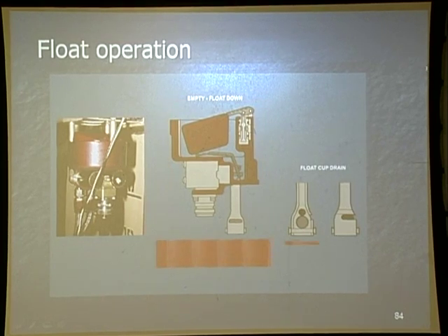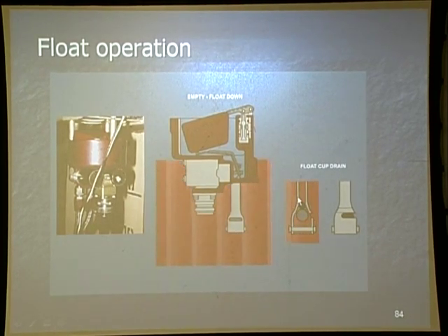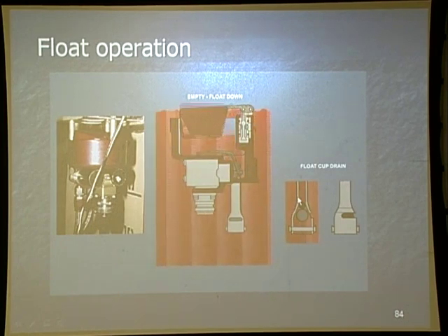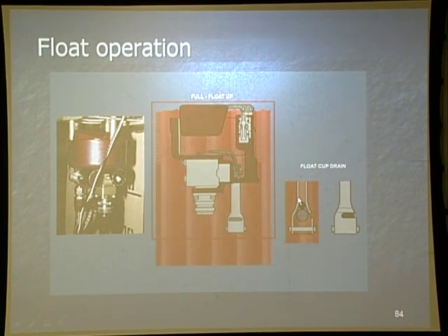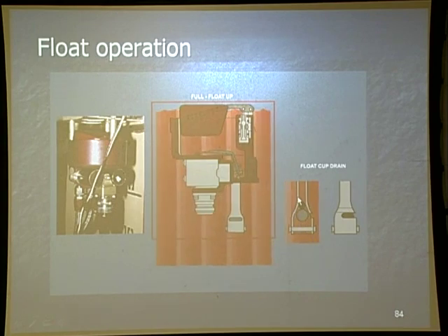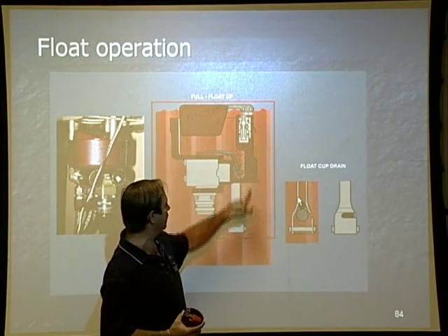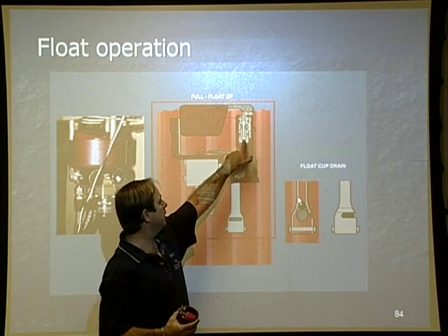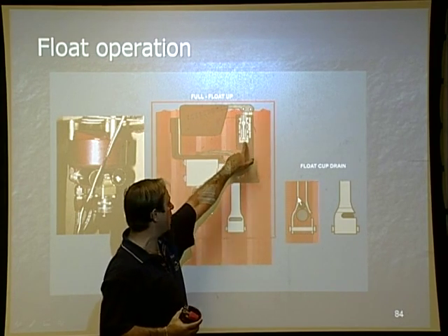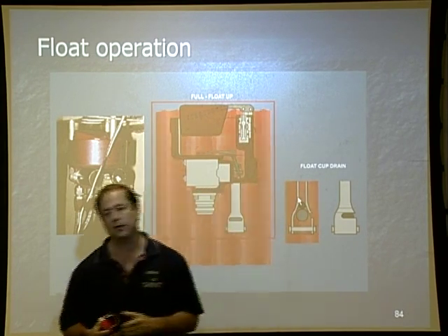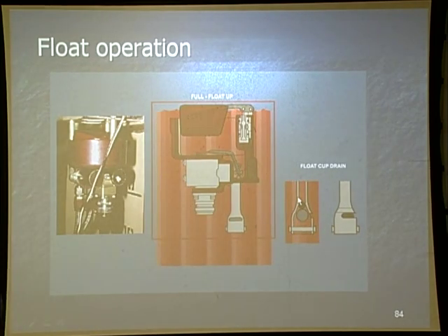What's going to happen is, as fuel comes in, it's going to float these 2 balls up. As it floats it up, it's going to come up. Fuel's going to go in there, floating it up. And what happens is, it's going to restrict fuel, because in this valve closing, it's going to create a back pressure that's going to result in closing this valve.